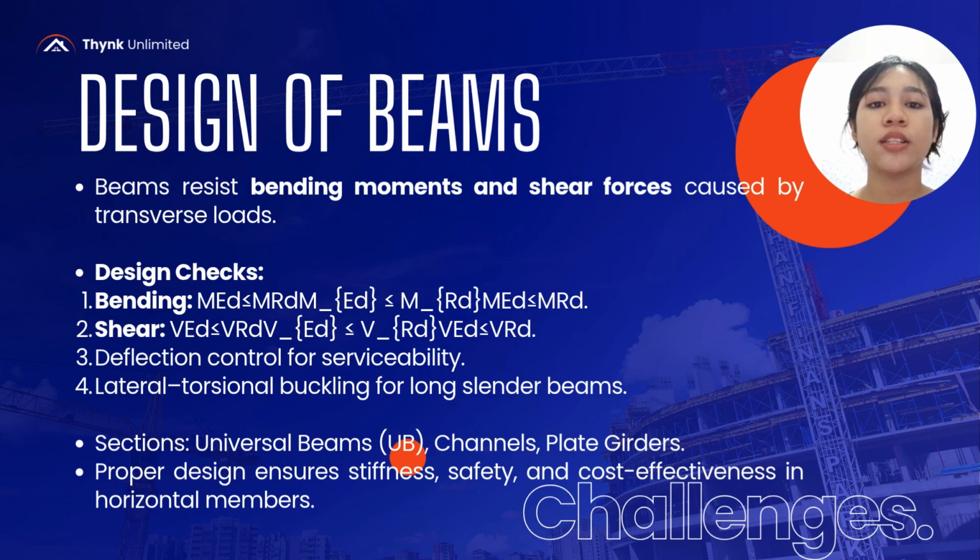Next, we look at the design of beams. Beams are structural members that resist bending moment and shear force caused by transverse load. For the design check, number one is bending check. We compare the applied bending moment MED with the design bending resistance MRD. The goal is to ensure that MED is less than or equal to MRD. Number two is shear check. We ensure that the applied shear force VED is less than or equal to VRD, the design shear resistance.